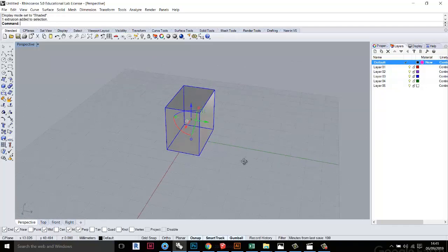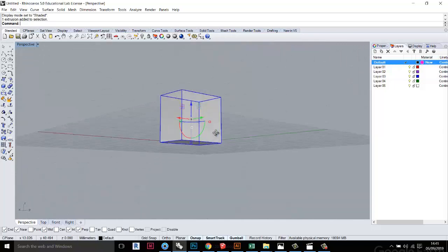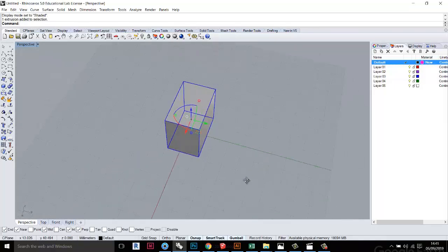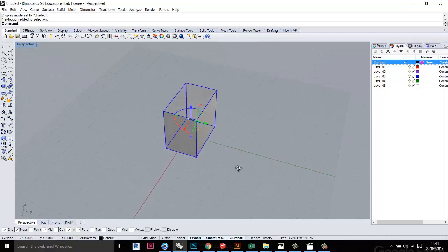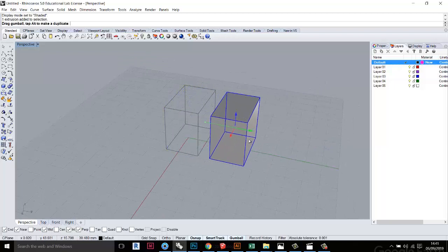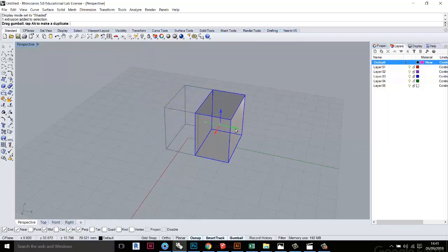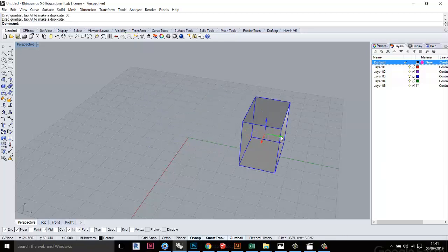If you select an object, gumball can then rotate and orbit around the center of that selected object, which is very useful when you're navigating through a model. As you can see, you've got move bars. You can start moving, point it in a direction and type an amount, 50 in this case. So if I wanted it just to move 2 mil, I can just start moving it a little bit and type 2, and I'll only get a 2 mil move, which is quite nice.